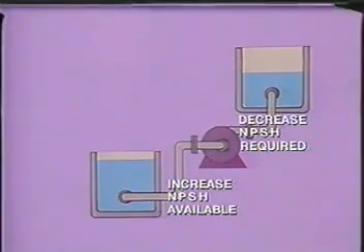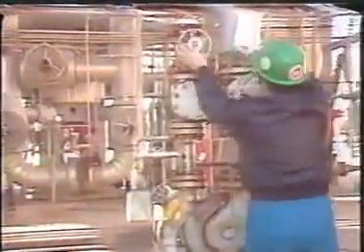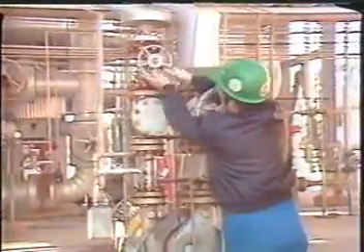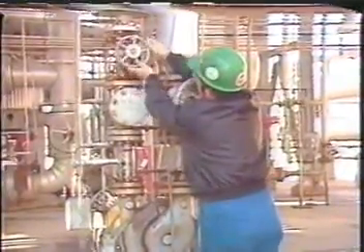of the pump. The net positive suction head required may be decreased by throttling or closing slightly the discharge valve, thus reducing the liquid flow. In any case, cavitation is a serious operating problem and will lead to mechanical failure if allowed to continue.